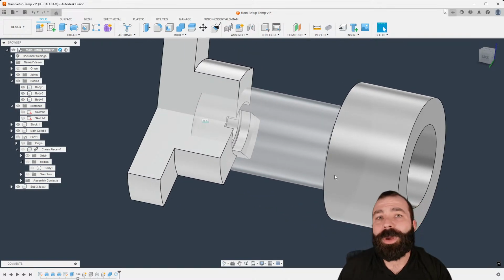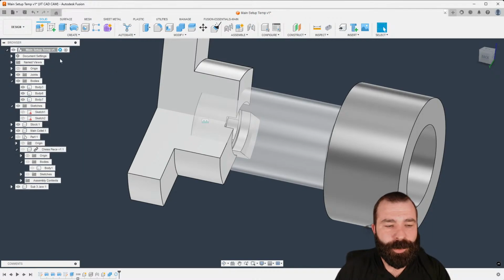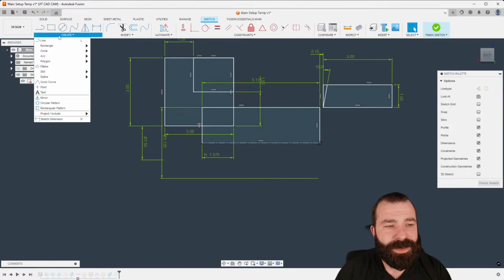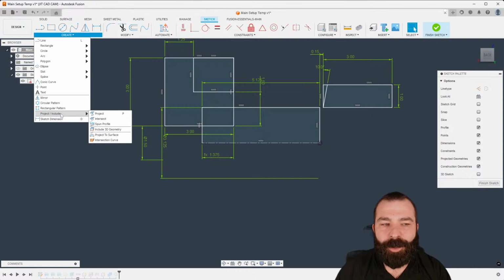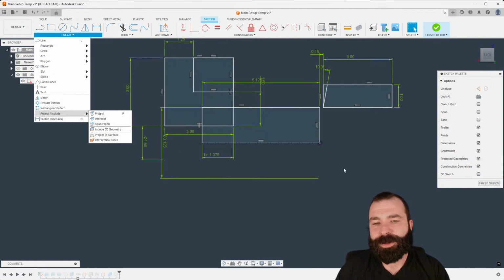So we do know with round parts, everything is just a spun profile. Now, if you guys didn't know, inside of Fusion you actually do have a spun profile tool as well. So if you're doing some more intricate lathe work, there is the ability to create a spun profile projection of your part. This is something a lot of people don't realize inside of Fusion: if you wanted to project a weird shaped profile to create round jaws, it's completely doable.